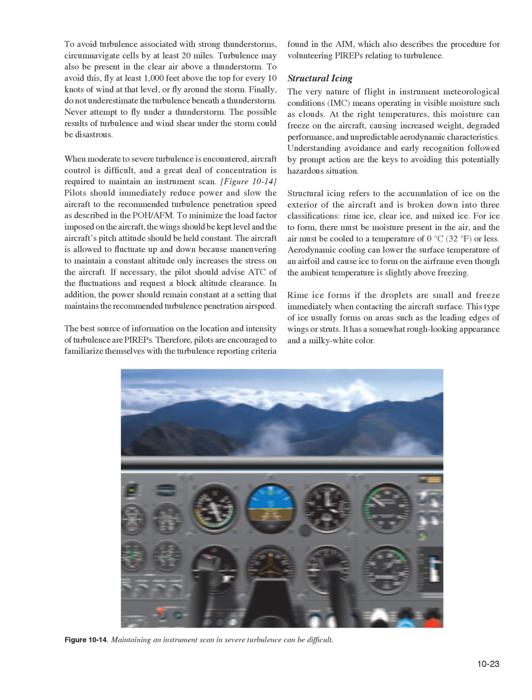Structural icing. The very nature of flight in instrument meteorological conditions (IMC) means operating in visible moisture such as clouds. At the right temperatures, this moisture can freeze on the aircraft, causing increased weight, degraded performance, and unpredictable aerodynamic characteristics. Understanding, avoidance, and early recognition followed by prompt action are the keys to avoiding this potentially hazardous situation. Structural icing refers to the accumulation of ice on the exterior of the aircraft and is broken down into three classifications: rime ice, clear ice, and mixed ice.